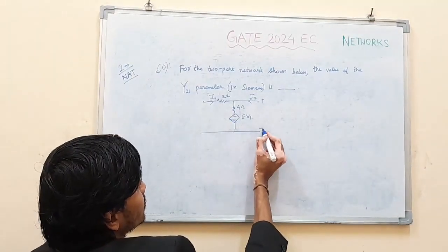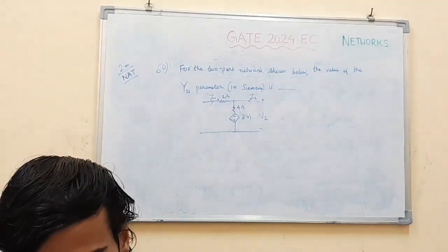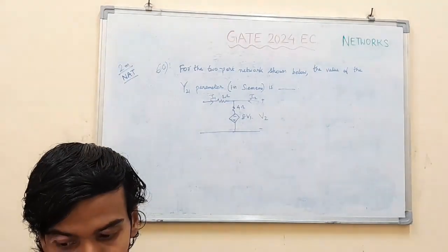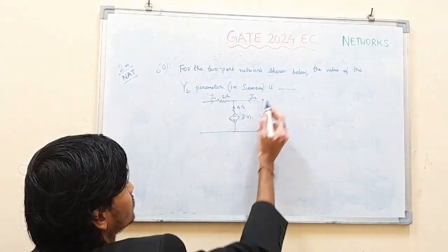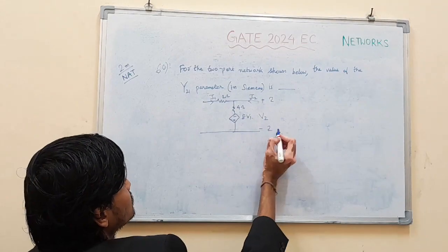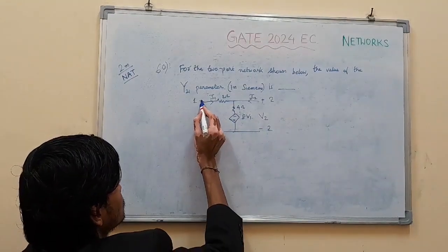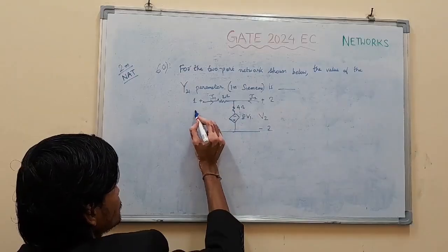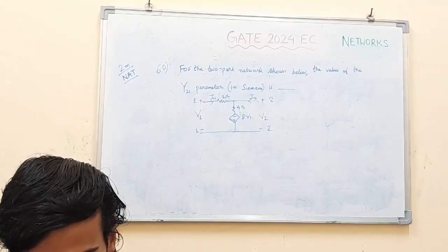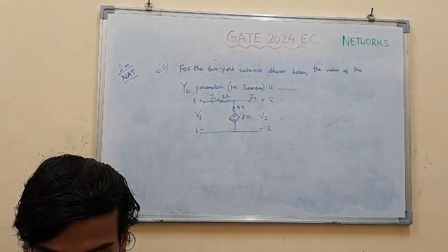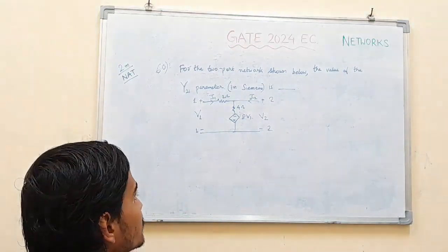Okay, this is V. Now this V is again applied across this branch. So current I2 will be V minus Vx by 2. Putting V in terms of Vx, with 5Vx by 3 minus Vx by 2: 5Vx by 3 minus Vx is 2Vx by 3, divided by 2. The 2 cancels, so it will be Vx by 3. So I2 is also equal to Vx by 3, same as I1.